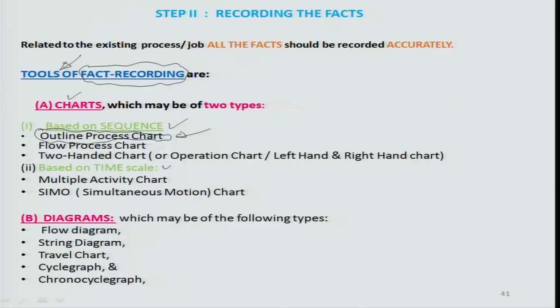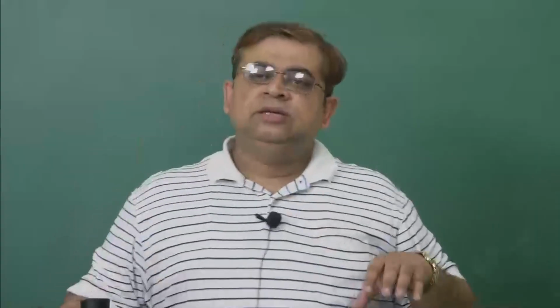outline process chart typically includes two different kinds of motion. One is associated with a process, and another is associated with an inspection. Okay. So, you are basically laying out the whole process in terms of those where the process contributes to the value, and another is that whatever contribution has been made by the process is being evaluated. So, a process and an evaluation. So, this kind of an outline schematic would lay out what are the different processes and what are the different value evaluating mechanisms which are involved in carrying out a full process. So, a process is described in terms of those symbols.